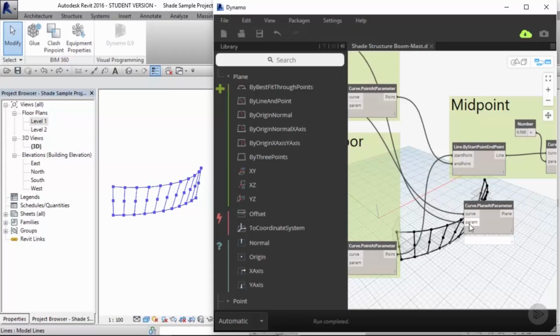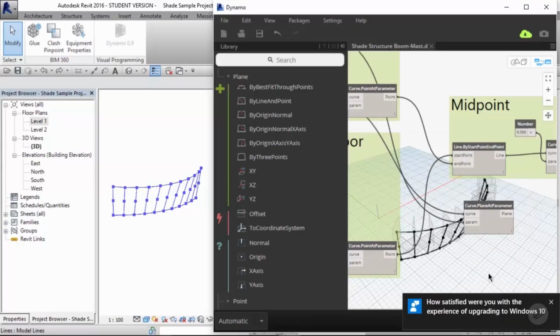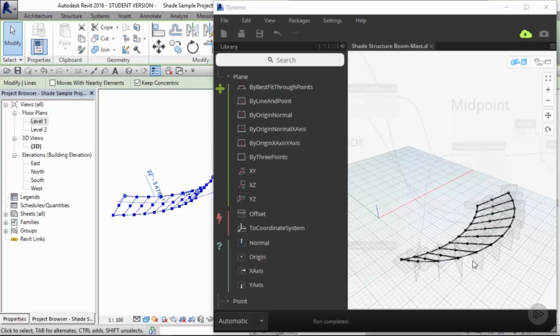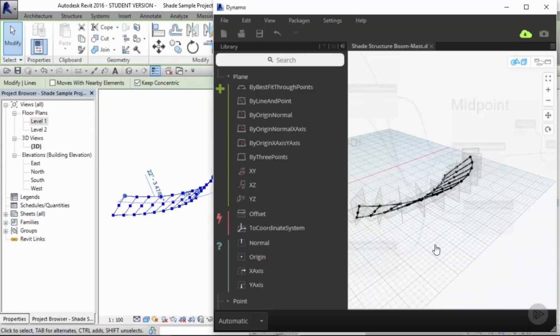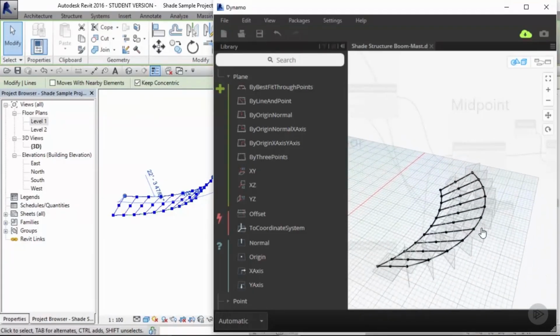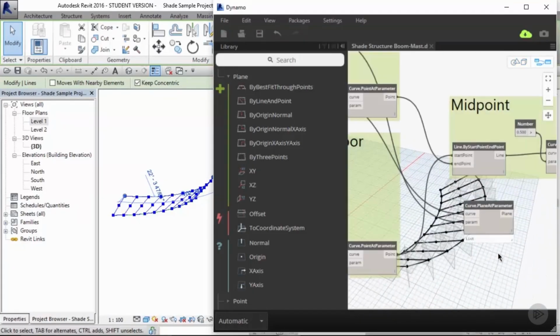However, when this is plugged in, what happens is those planes are aligned to whichever curve I choose. In this case, I chose the top curve, and it looks like it's aligned properly. If I rotate around, it looks like the y-axis is approximately aligned with the vertical mast that I've generated. However, if I move now my model curve to a tilted position, the plane now does not rotate. It will move with it to the new position, but it does not rotate out of the XY orientation.